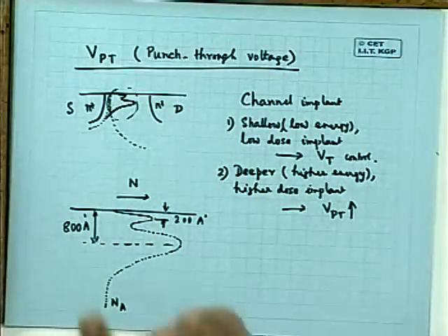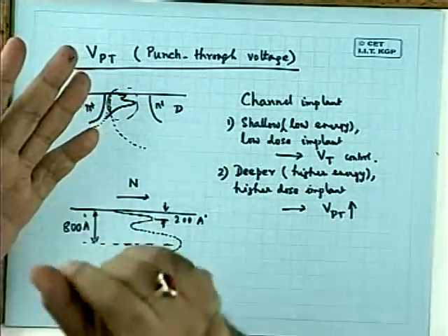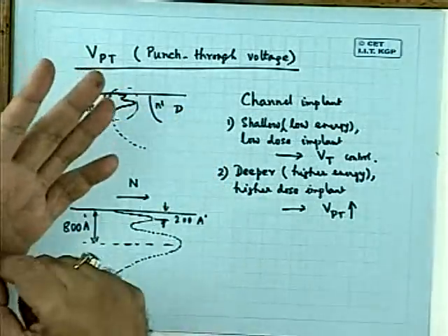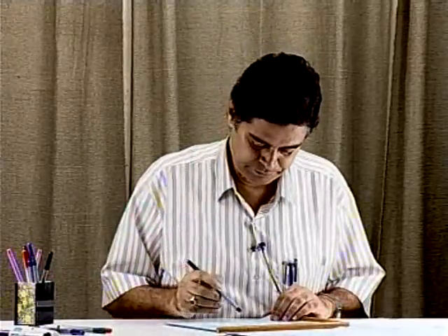It's not only the power supply; there is always a fluctuation tendency. If it is 5 volt, always design for 10 volt. If it is 3 volt, design for 6 volt minimum. If it is 1 volt, design for 2 volts minimum. If you do not do that, a small fluctuation will result in breakdown. So if doping is not uniform, then the breakdown is lower. Yes, in these two channels, breakdown voltage increases.